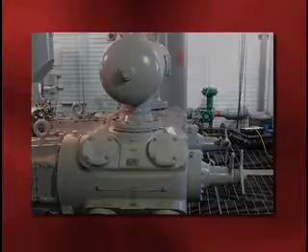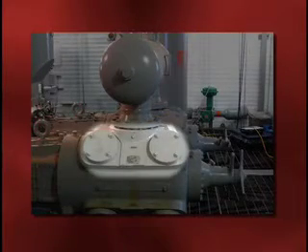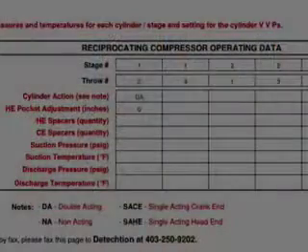The head end and crank end spacers are the number of valve spacers or split yokes that are currently installed under the suction or discharge valves on either the head end or the crank end of the cylinder.